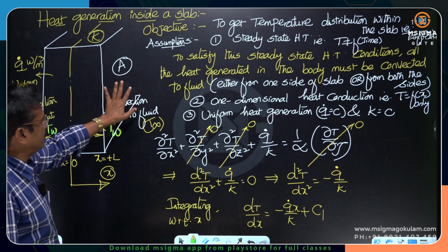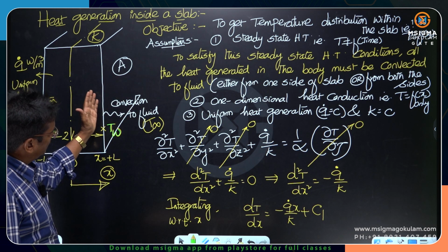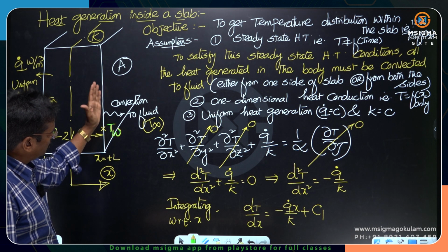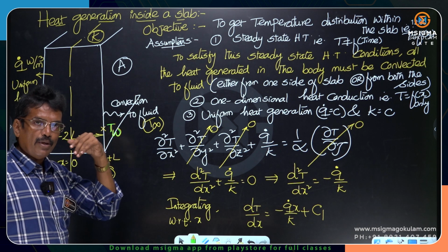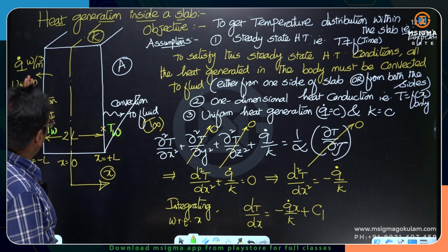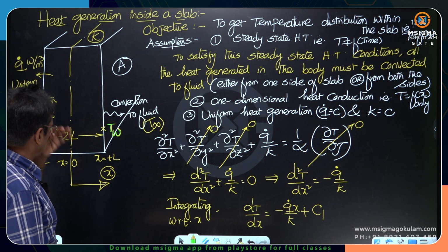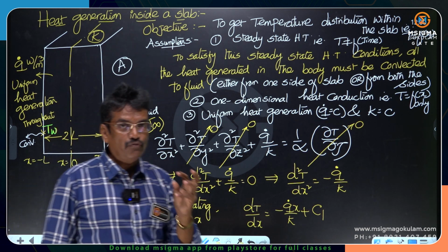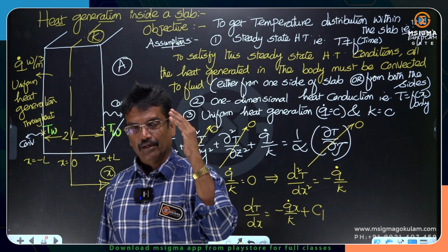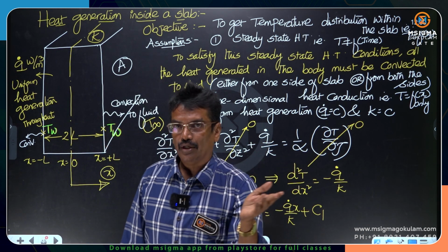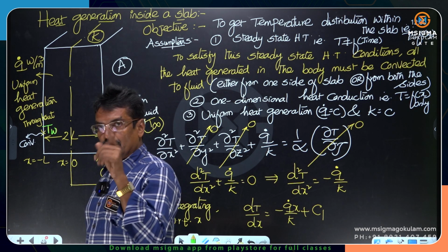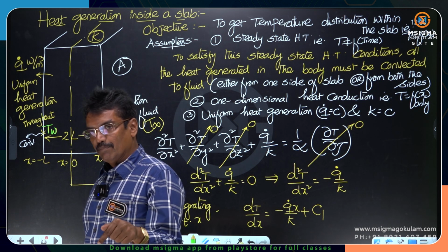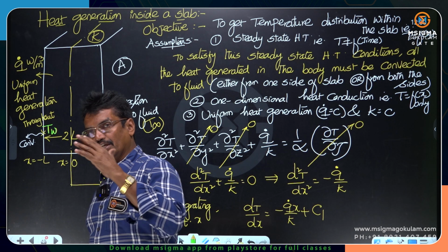Obviously, the air side, whatever surface is in contact with the air, will have more temperature as compared to that side which is in contact with the water. Supposing both sides air, but one side you have forced convection, wind is there, and the other side there is free convection. So, obviously, the forced convection side will have the lower temperatures because air is taking the heat rapidly.